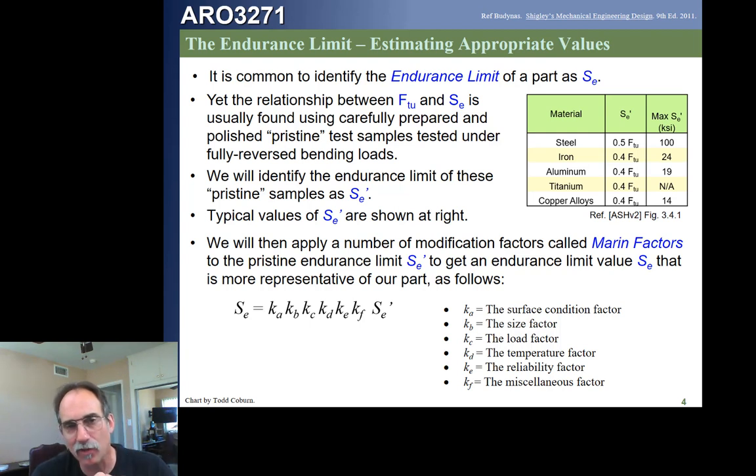How much reliability do we want in our answer? How close do we want to get? Since we have scatter with all data, any value we use has a chance of being wrong. If we want to reduce the chance of being wrong, we can use a higher reliability, which doesn't change how the material behaves, but changes how much credit we give for how the material behaves.